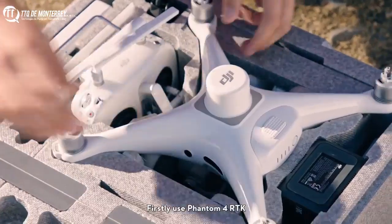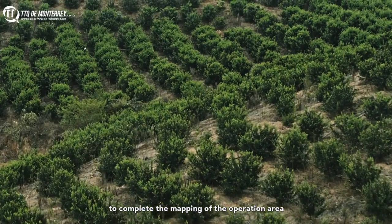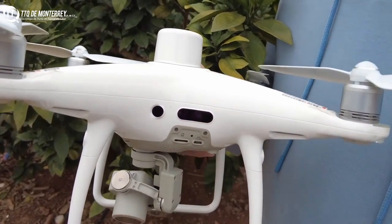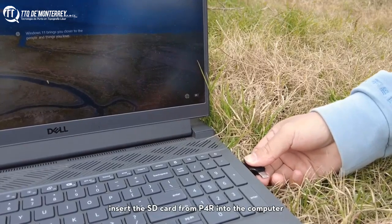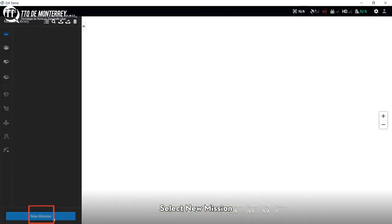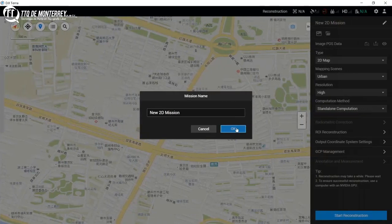Mapping. Firstly, use Phantom 4 RTK to complete the mapping of the operation area. Import pictures into the computer for 3D reconstruction. After mapping, insert the SD card from Phantom 4 RTK into the computer. Open Terra. Select New Mission and select 2D map.